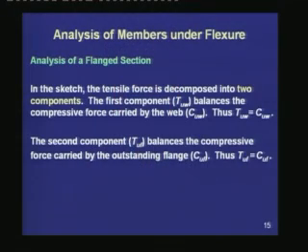In this previous sketch, the tensile force is thus decomposed into two components. The first component, TUW, balances the compressive force carried by the web, which is CUW. Thus, we have an equation TUW is equal to CUW, because they are under equilibrium.